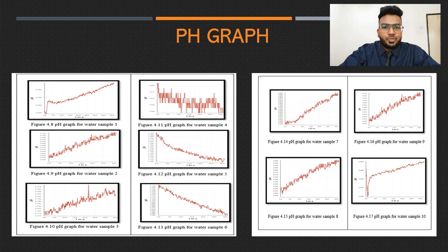posing additional indirect dangers. For Malaysia water quality standards, pH values between 6 and 9 are classified as Class 2A and 2B. Class 2A is mainly about conventional treatment and fishery 2 is concerned with the delicate aquatic species. Class 2B is for bodily contact as a recreational activity. Data obtained from the pH test of 10 filtered water samples: the lowest pH value is 6.27 and the highest pH value is 7.13. The pH value does not go below 6.27.